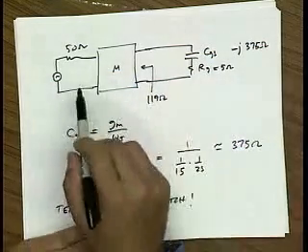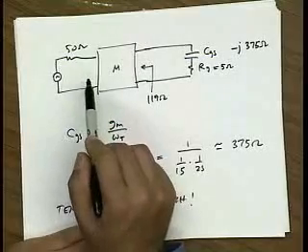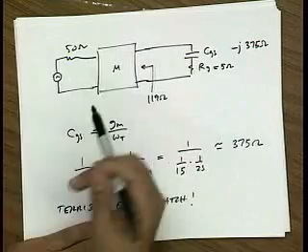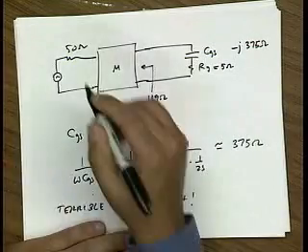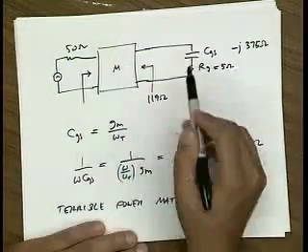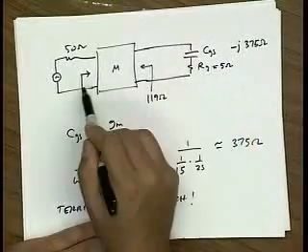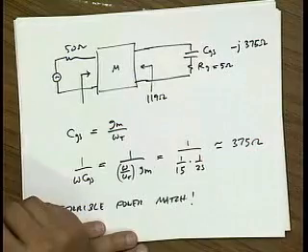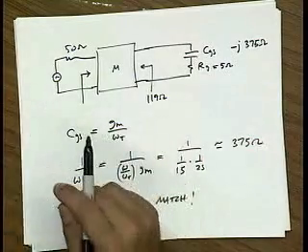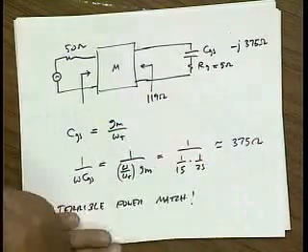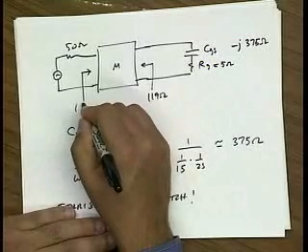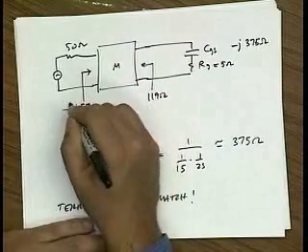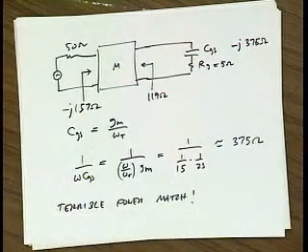First of all, you don't hook up the input directly to the antenna. You usually go through a filter, and that filter needs to be terminated with 50 ohms in order to work. What does the filter see? Well, the filter sees this impedance transformed down by the ratio of 119 over 50, which is about 2.4-ish. So looking into here, I see about 157 ohms, but minus j, capacitive.